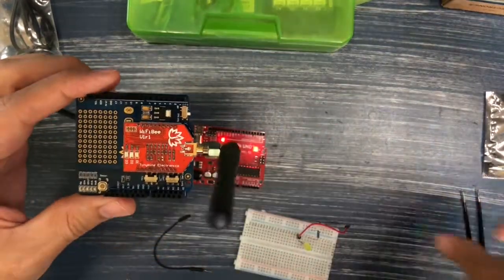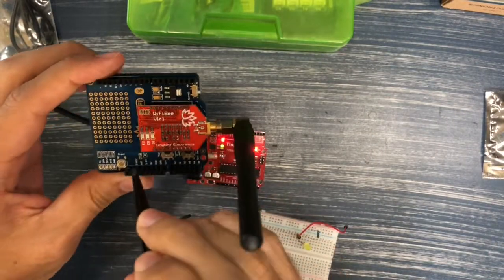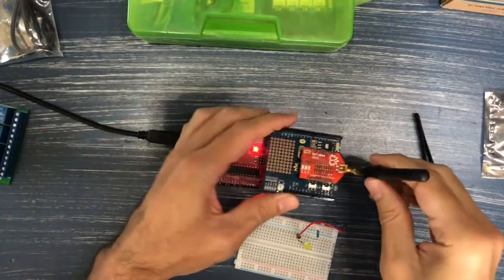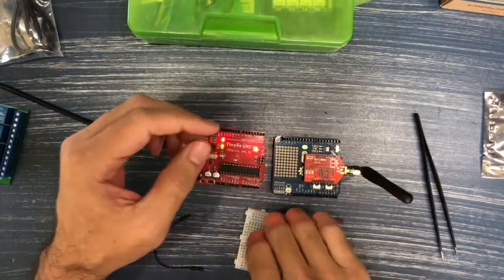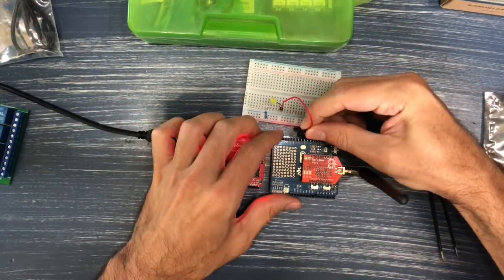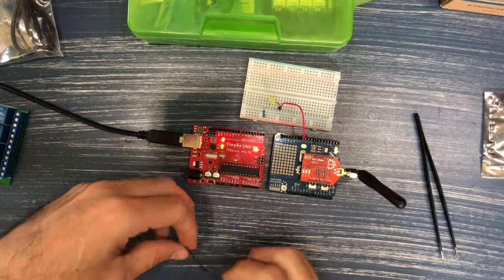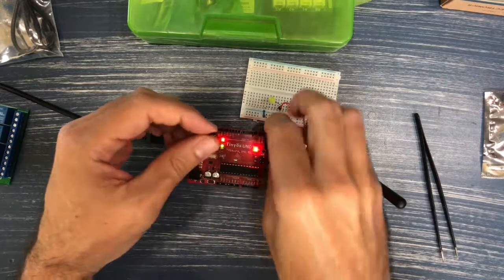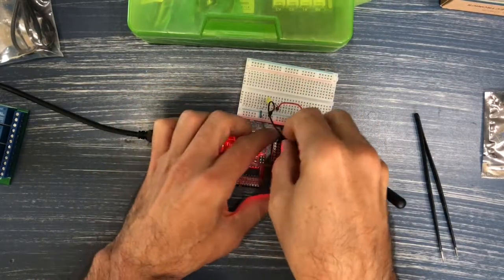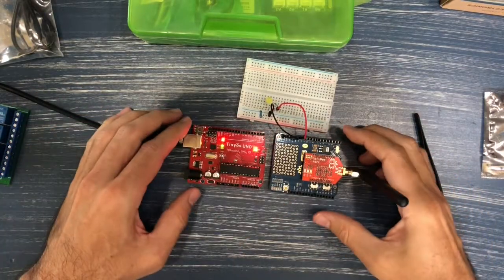So let's do our regular wiring. This has the same pin out as the Uno, and pin 12 is where we're going to actually connect our LED. So instead of giving it 5 volts red, we're going to be giving it pin number 12. So only when we set the pin to high is it going to get power. The other end of the leg, which goes through the resistor to ground, is going to connect to the ground pins. Okay, there it is.